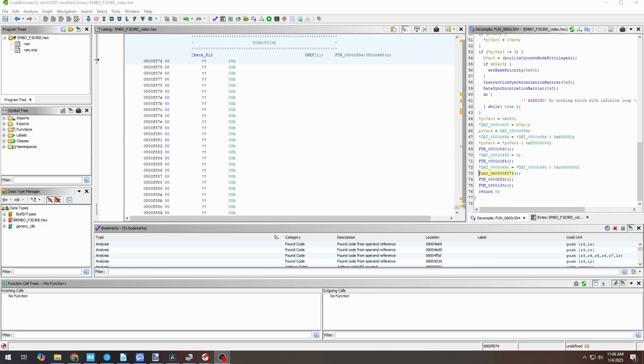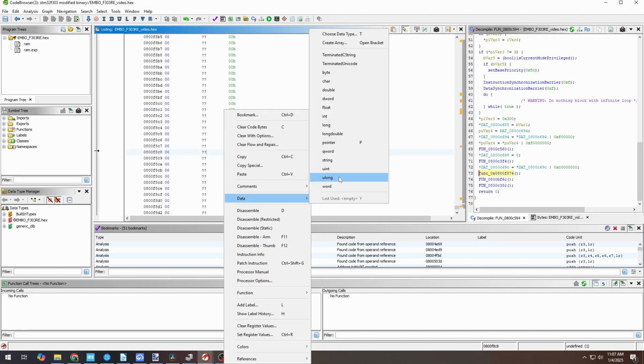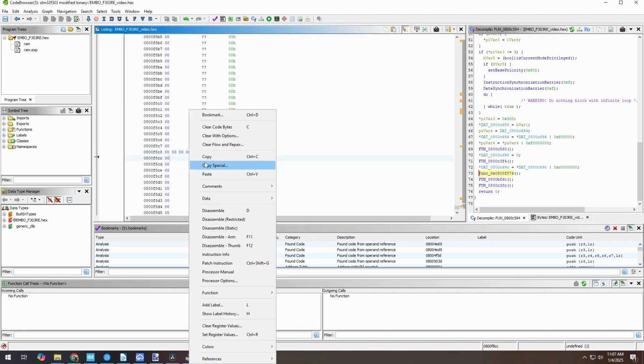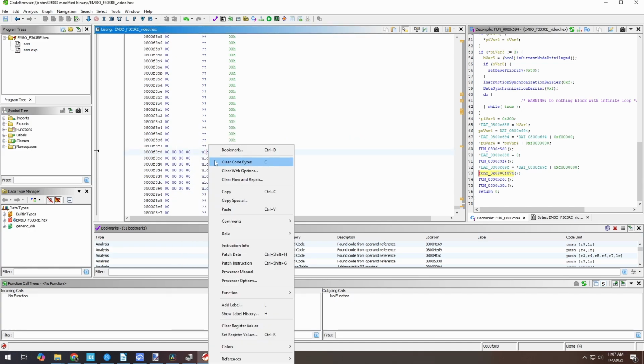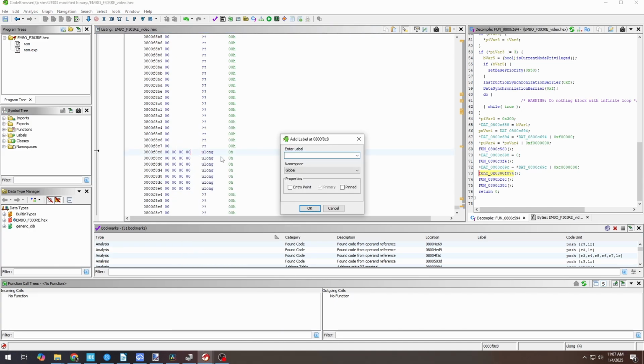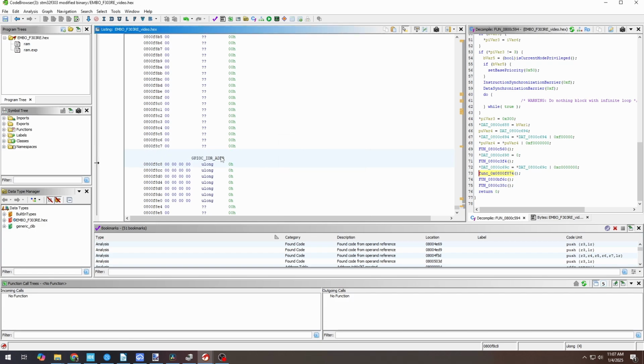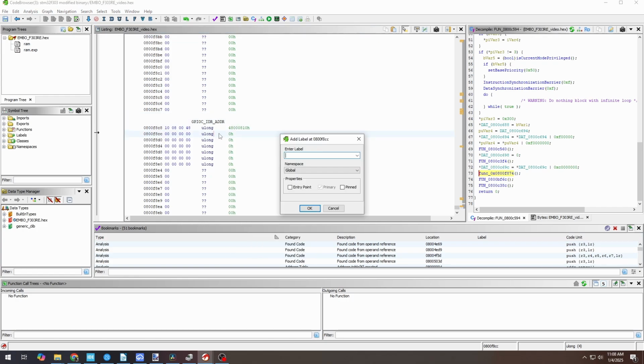And so I already know the addresses, and so I'll just hard code them in right now. You could hard code the addresses into instructions, but I'm actually just going to put in values that the computer's going to grab later. I'm going to navigate down to F8C8, and we'll make a bunch of unassigned longs here. So the first thing that we're going to need is the GPIO-C input data register address. And this is how we're going to get information about the pin state of PC12. And that is located at 0x48000810, or hex. And I'll go ahead and just hard code the rest of them in.